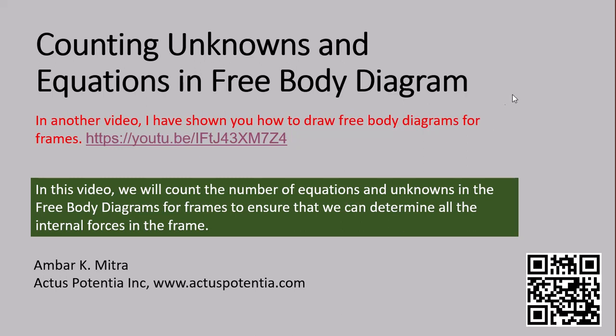In this video, we will count the number of unknowns in free body diagrams and count the equilibrium equations that are available to determine the internal forces in a frame. The number of equilibrium equations must be equal to the number of unknowns, the unknowns being the internal forces when we draw the free body diagram of the members of a frame.